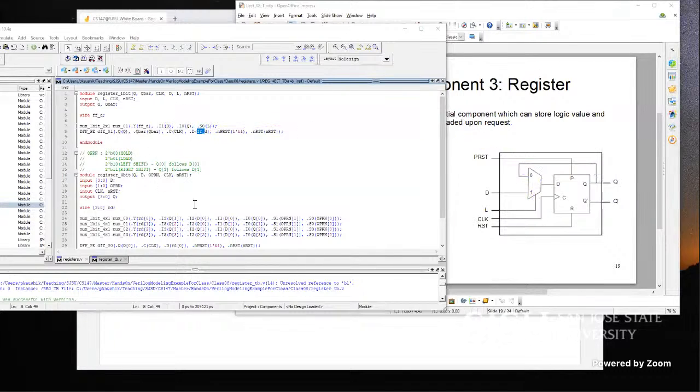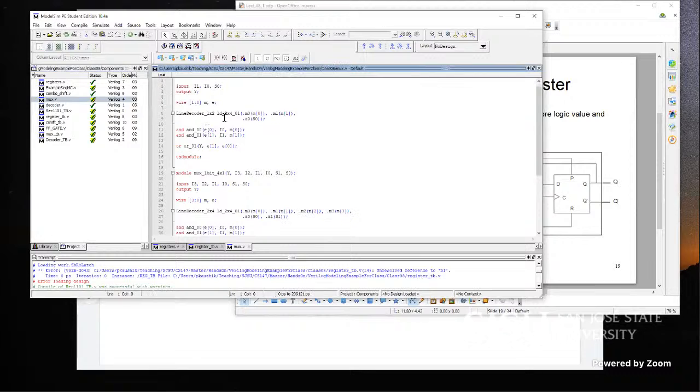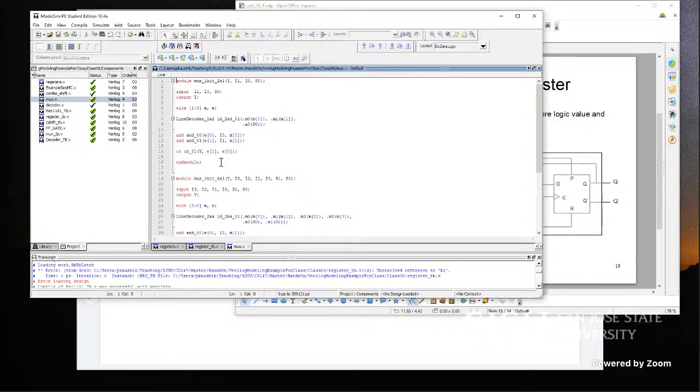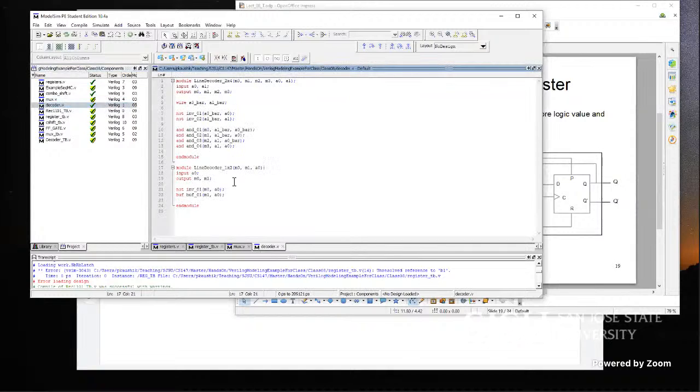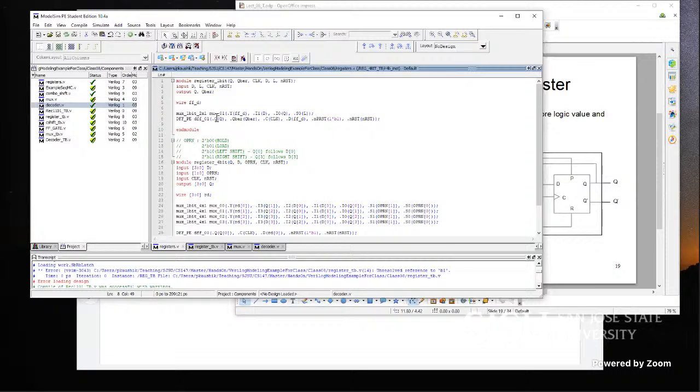So this is what we define, a very simple gate level register. And of course, if we want to explore the definition of the other part, we have this multiplexer code here, 1-bit 2 to 1, which instantiates a line decoder with some AND and OR gates around that, and the line decoder being implemented at this point, a 1 by 2 line decoder, gate level implementation. So this is more like a hierarchical definition of this hardware module. In reality, it is just like this.